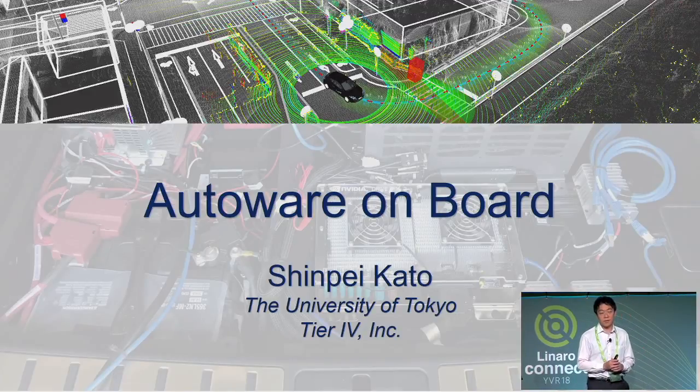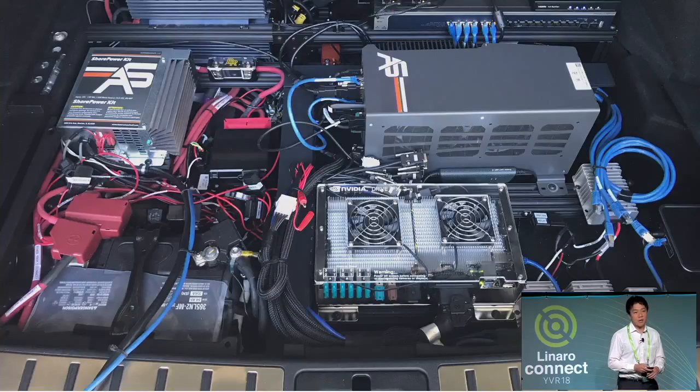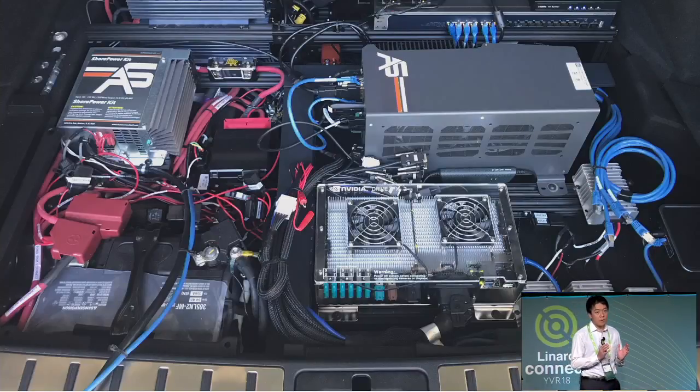Autoware is open source software for self-driving, not only on your desktop, but also in a real car using an automotive specific board. We actually use this software ourselves as well for a lot of field testing. We equip the facilities such as small computers, network switches, batteries, etc. And Autoware is installed and controls the car. The car is modified to receive commands from the computer. Autoware is kind of a brain for the self-driving technology, so it sends a command for how the car should move.